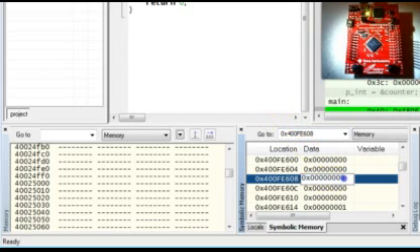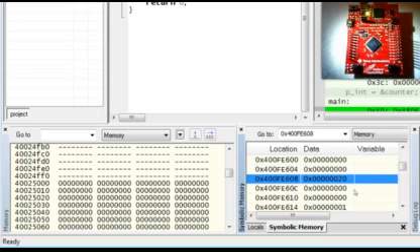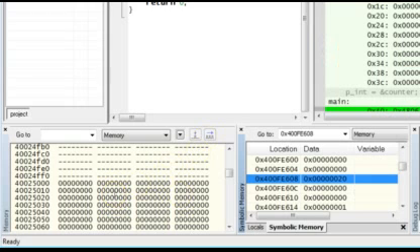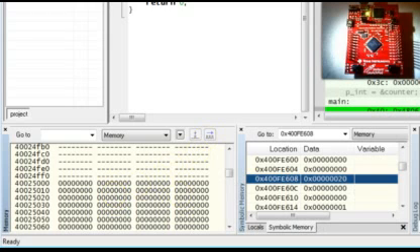Now go to the highlighted clock gating register and edit its value to set bit 5, which, as you remember from lesson 1 about counting, is 20 hexadecimal. Hit enter. Hey, the GPIO F hardware block wakes up. You are getting really close to being able to blink the LED, but you are not quite there yet.